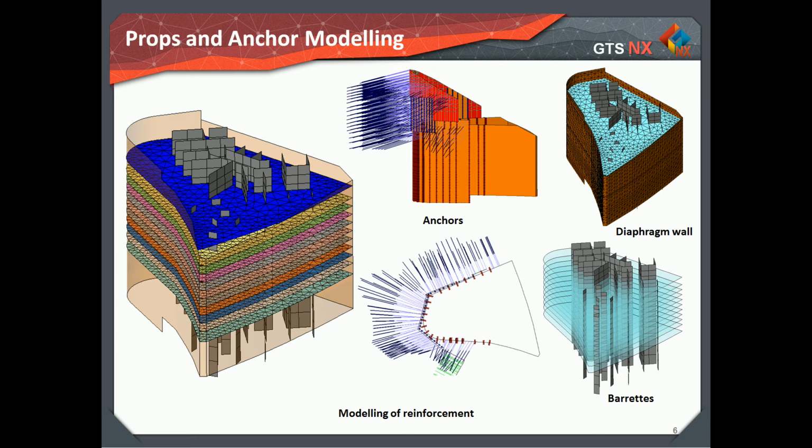Anchors can be modeled by bar elements, and it is relatively easy for the program to calculate the excess force over the initial value. Beam elements have rotational as well as displacement degrees of freedom and therefore are capable of transmitting moments as well as axial force.